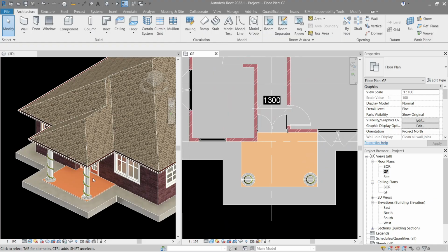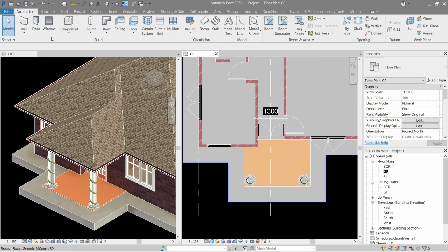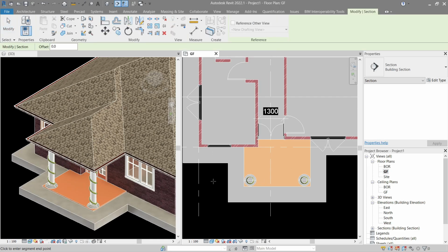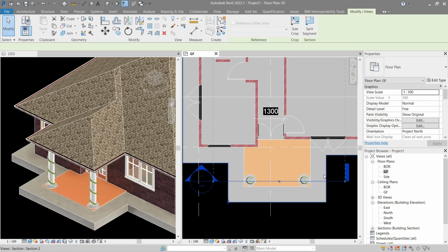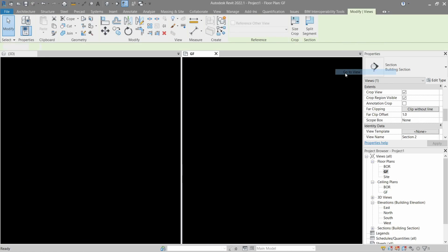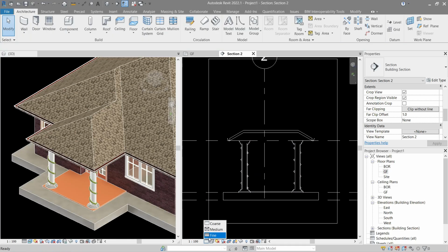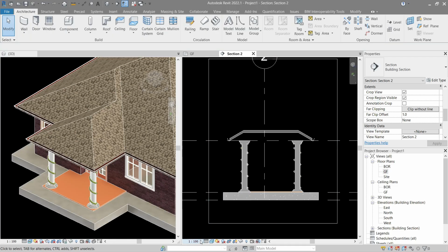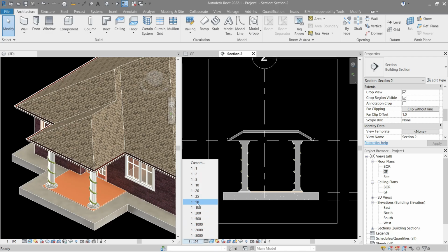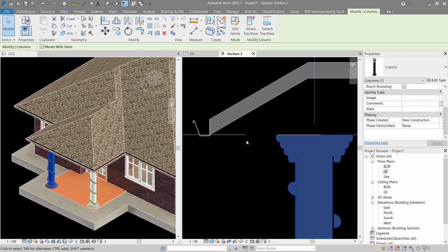Okay, now to see if it perfectly aligns, we're going to use a section view. Reduce the range. Let's make it 1. Right click, go to view. It's black and white. Let's change this to fine, shaded. Let's change the scale. Okay, it's touching the level.